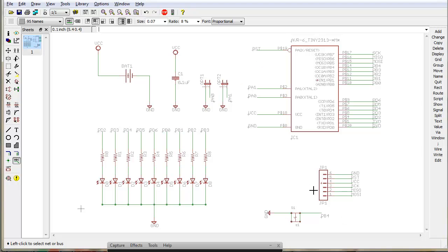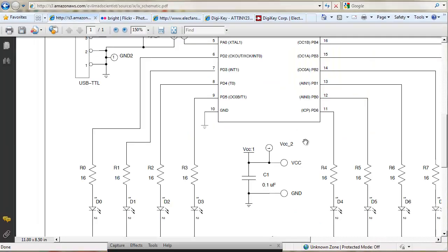I forgot to put the VCC onto the jumper, and although it was here and there and it was before the battery was added, it meant I had to add a little wire to it, and I'll actually show that to you in a little while. So yeah, power is a really important thing to check, and because I designed the schematic this way, where I just have these little sections, you can kind of miss things. But even when you do it as the other style, which is this type, you can still miss things because, as you can see here, things are split up.